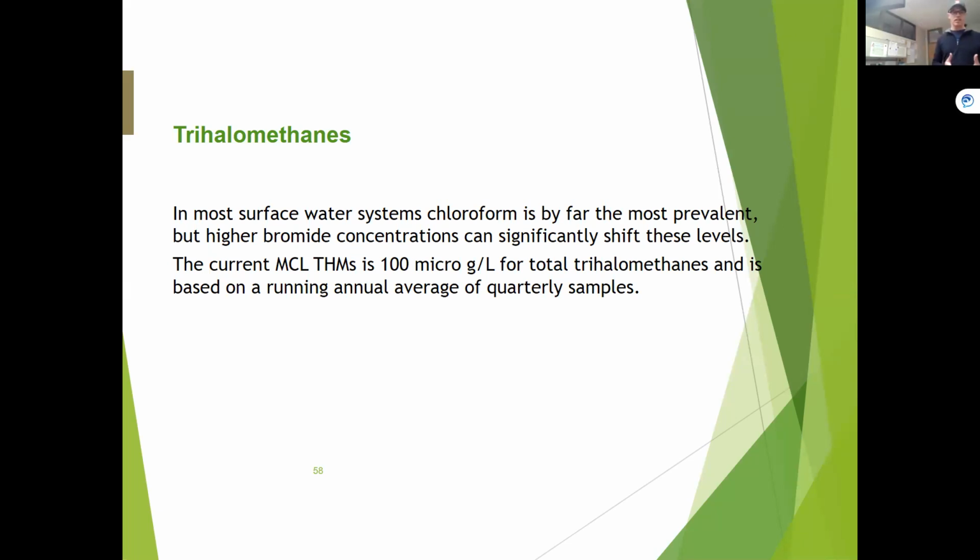For those of you who have rechlorination out there in your systems, that also can add to trihalomethane production, right? So maybe halfway through your system, you're reintroducing chlorine. That could also have a definite effect on trihalomethane production. So keep that in mind. Where I see it right now is, like I told you, I've had all winter very low flows, and now my flows are starting to come up because people are turning on their irrigation. That causes right away a lot of organic material to get moving in the mains out there, and combining that with the chlorine, we get into some troubles here.